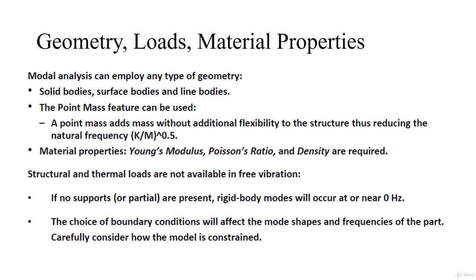And coming to loads, no structural or thermal loads can be applied in the free vibration analysis. Any type of structural or thermal loads we cannot apply directly in modal analysis. And then if the supports of the body are not given, the body moves in a rigid body fashion.